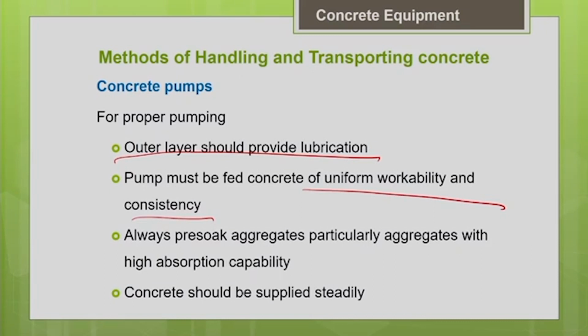Another important thing is if you are going to use lightweight aggregates for making concrete and that concrete is going to be pumped, you know that lightweight aggregates have a higher water absorption capacity. So when you use that kind of lightweight aggregate concrete for pumping, under pressure the aggregates will absorb more water.